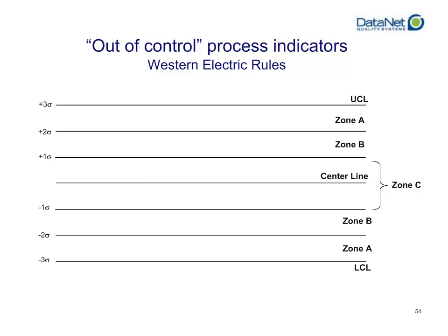So going from left to right, the different out-of-control process indicators that you might see according to the Western Electric rules are the 1 point beyond zone A, meaning even a single subgroup of data that falls outside of zone A is a cause for investigation, and an assignable cause is possibly in play. The next out-of-control indicator in this set is the 2 out of 3 points in zone A or beyond. While we would expect that data points would fall within plus or minus 3 standard deviations of the center line, we would not expect it to happen 2 out of 3 times.